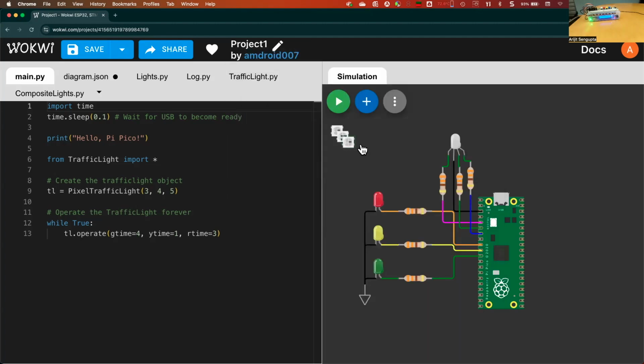All right, so now I've got three NeoPixels. What is nice about these is that not only do they have a chip inside, they also have the necessary current limiting resistance built in. So you do not need to worry about adding the current limiting resistance that we had to do for light strips. And also, these LEDs can be daisy chained one after the other.